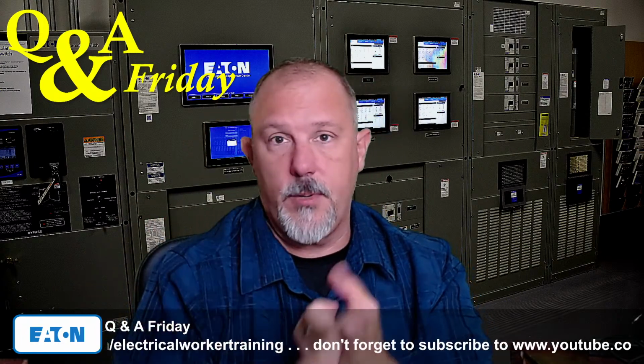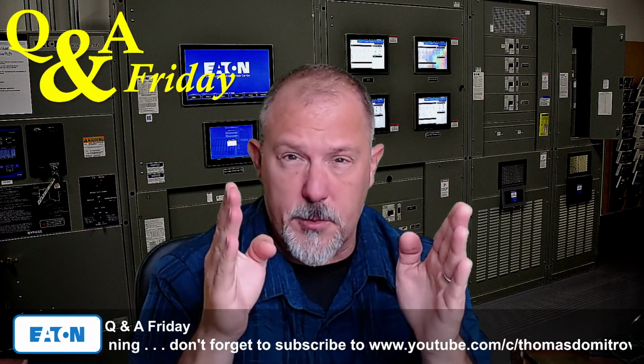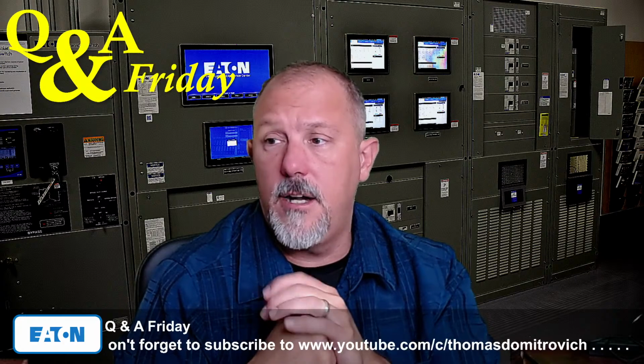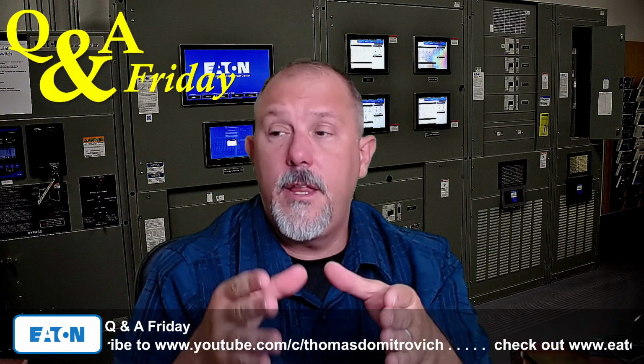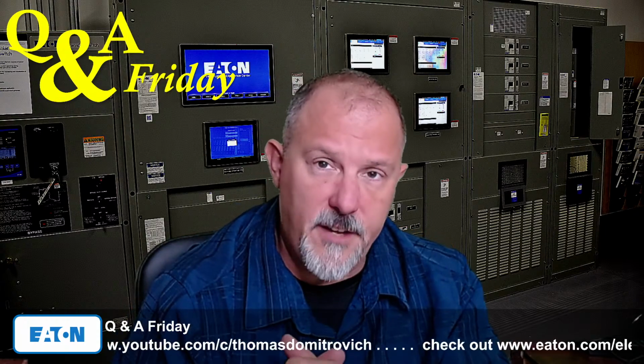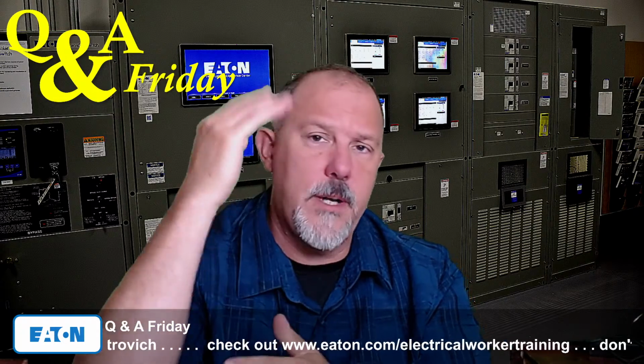You can put presence of voltage indicators in the top. You can put a window in the top so you can visibly see the disconnect of the blades, and that establishes an electrically safe work condition in the bottom cabinet where you are replacing fuses, or if you're doing any monitoring in that fuse cabinet.